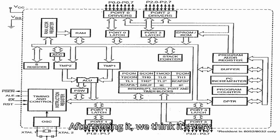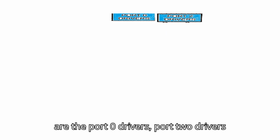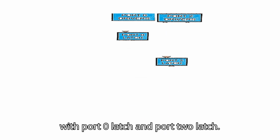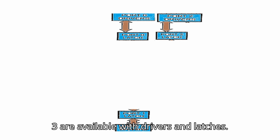After seeing it, we think it's very difficult. Yes, it's difficult, but I am telling you how you can remember this. Let's go. 8051 has 4 ports, 2 at the upper side and 2 at the lower side. At the upper side, port 0 and port 2 are available. These are the port 0 drivers, port 2 drivers with port 0 latch and port 2 latch. Same at the bottom side. Port 1 and port 3 are available with drivers and latches.